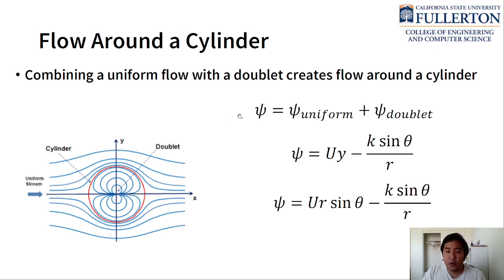And we can do a lot with this in terms of finding out pressures, of course, velocity distributions, things like that. So, this stream function concept and the ability to add together flows to make more complex flows is extremely valuable and one of the biggest strengths of potential flow as a technique.